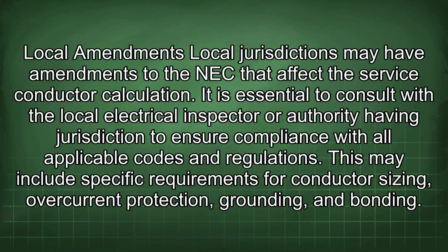Local amendments: local jurisdictions may have amendments to the NEC that affect the service conductor calculation. It is essential to consult with the local electrical inspector or authority having jurisdiction to ensure compliance with all applicable codes and regulations. This may include specific requirements for conductor sizing, overcurrent protection, grounding, and bonding.